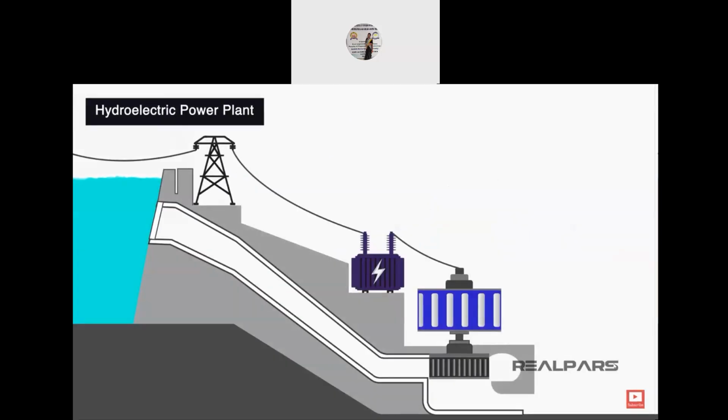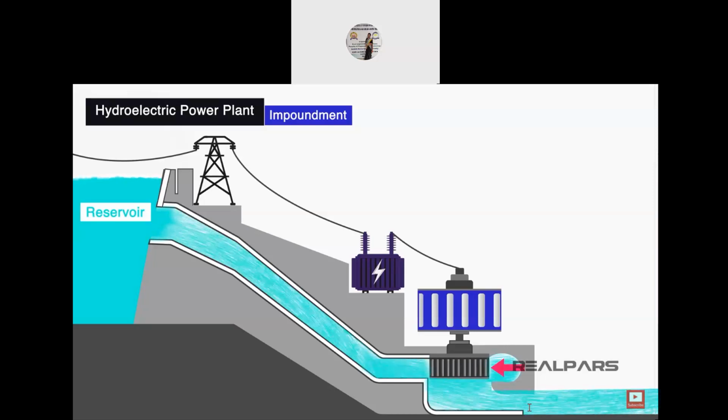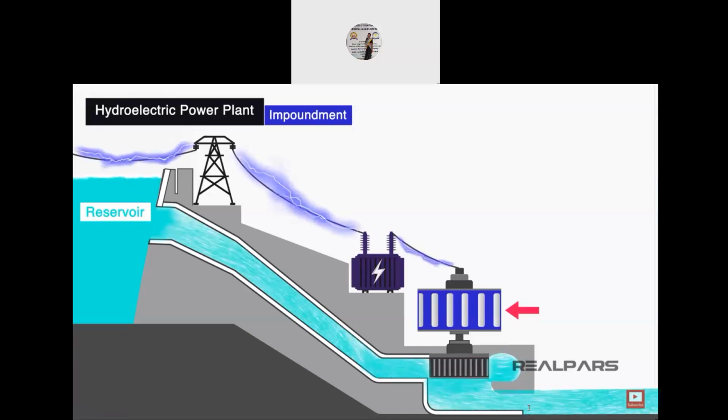Hydroelectric power plants generate power by converting the force of water to turn large generators. Hydroelectric power plants fall into 3 different categories. First up is impoundment. An impoundment facility typically uses a store of river water from a dam in a reservoir. When water is released from the reservoir, it flows through a turbine, which generates motion. This turning motion activates a generator to produce electricity.